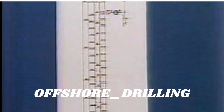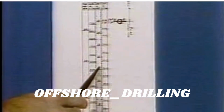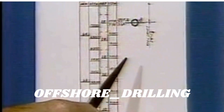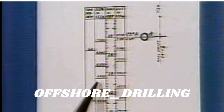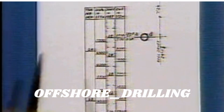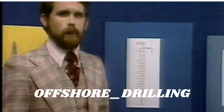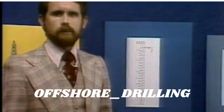The scale is usually entered with the vessel's draft, and then it is possible to read across the scale and determine the MT1, deadweight, displacement, and TPI for that particular draft. As an example, let's examine the deadweight scale for the SEDCO 445. A reproduction appears on page 11 of the SEDCO Self-Study Guide.